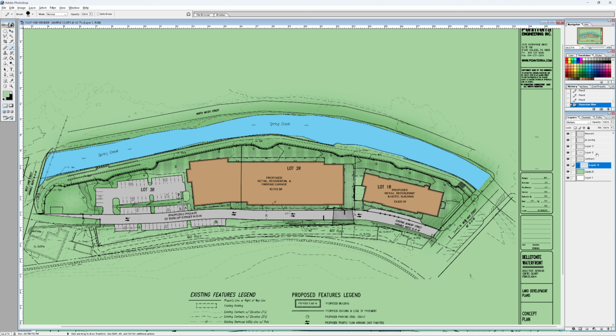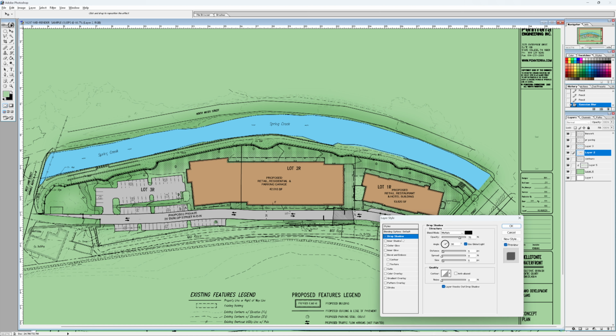So here, I'll add a drop shadow. You can set which direction the light is coming from. I usually look for the north arrow, and I set it so that the light is coming from the south. So you just match that to your north arrow. Then you can change your distance. Notice how I can move it farther away from the building. Doing shadows this way, they're not exact because they just move. This should have that angle in there closed in as a shadow.